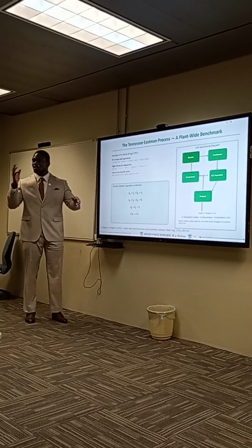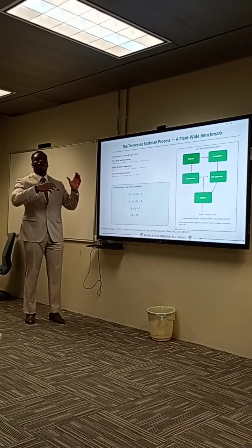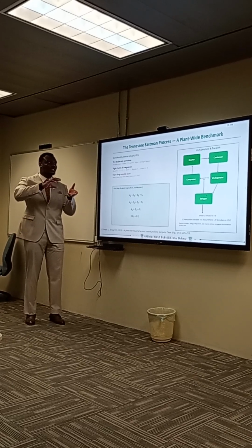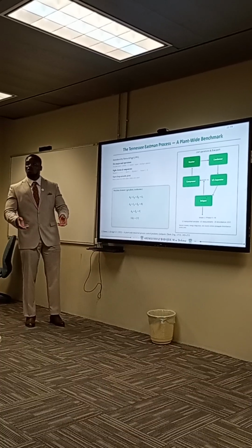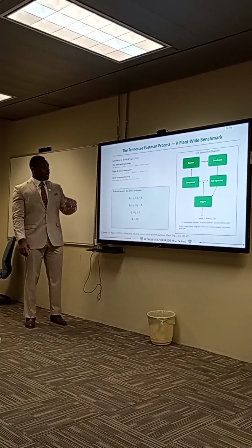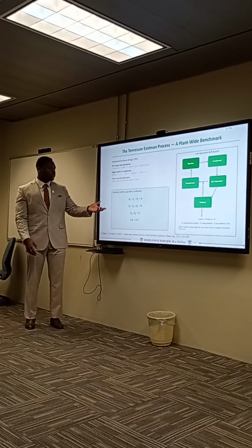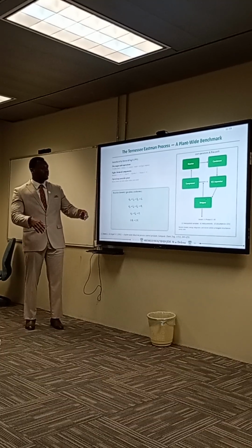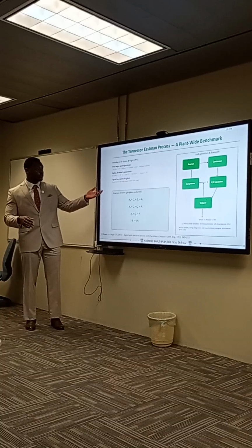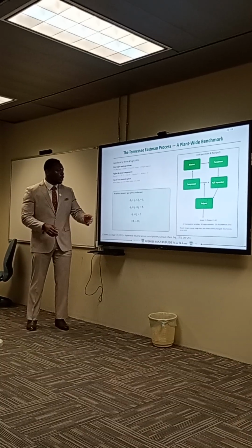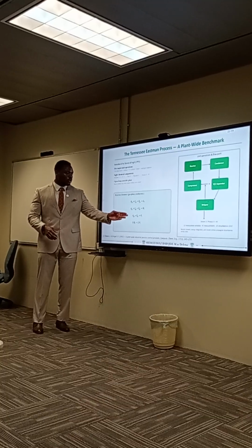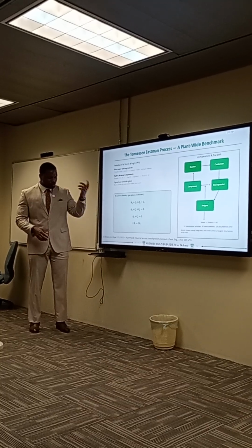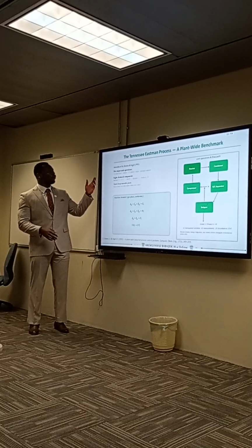Then you have several recycle streams, and it can be as complex as this, but this is a model to give us a platform where we can test our control strategies, especially in process control. It is guided by some reactions, A and C; it's generic, so there's no specific reaction regarding the chemistry. But it's good to know you have 2 given products, G and H. And you have inerts, or unwanted gases, in the plant, and several reactants.